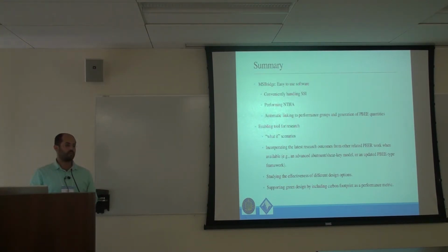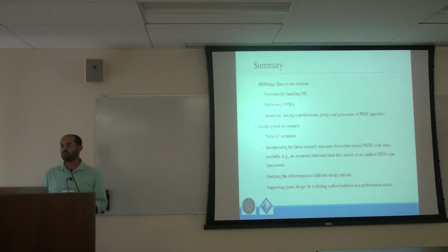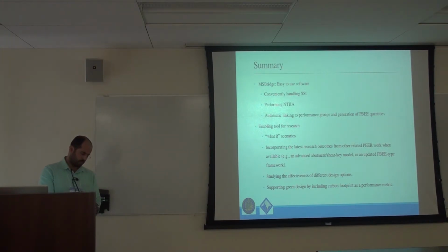It's a different example. What you're referring to is a parameter estimation problem, and I think for nonlinear problems, you can use something like unscented Kalman filters to estimate properties of these hysteretic models. But then again, it becomes almost intractable if you have multiple nonlinearities competing. So you first have to isolate the nonlinearity, then reduce the parameters by doing some smart sampling, and then apply a Kalman filter or something like that. I mean, that's also one of the things that's kind of lacking in the OpenSees arsenal or PEER arsenal, which is, what do you do with these sophisticated parameter estimation problems?